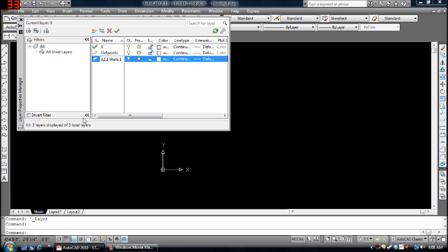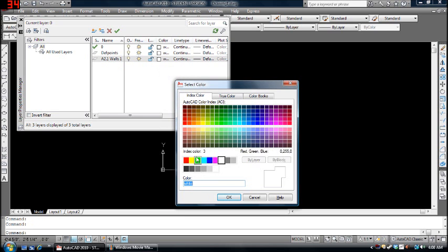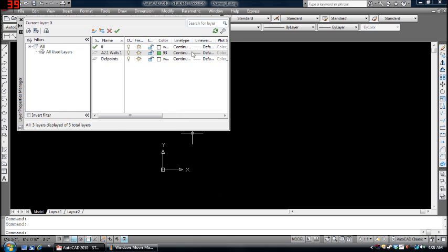Or what we're using right now is walls 1. So like 2.1 walls 1. 2.1 is just the name of your drawing, so 2.1 could be your sections, your elevations, your site, anything. Then you can change the color that you want. You can type a color like 93, I don't know what color that is, just guess. That's green.